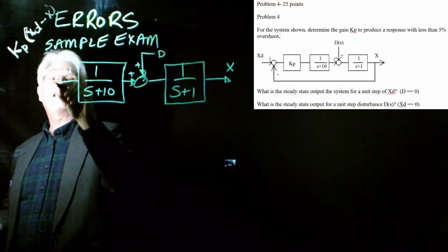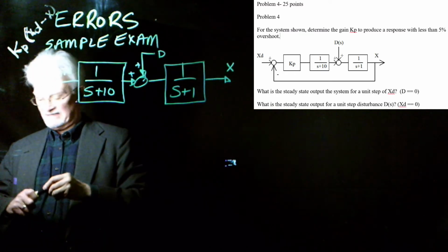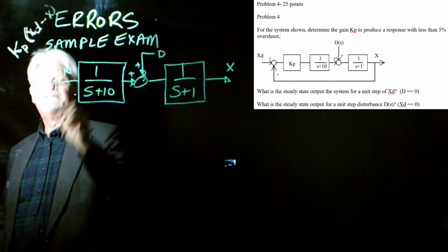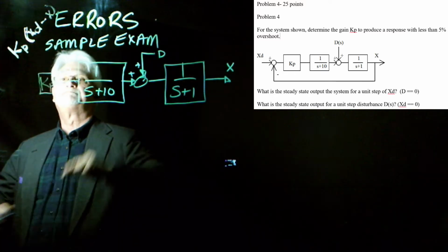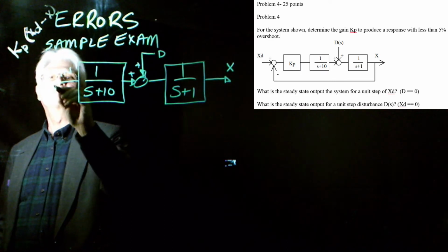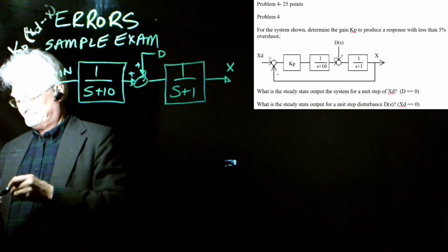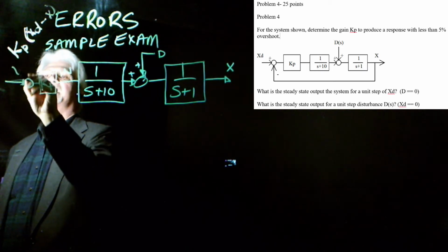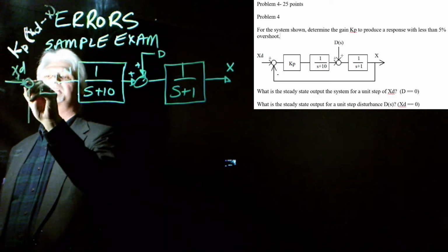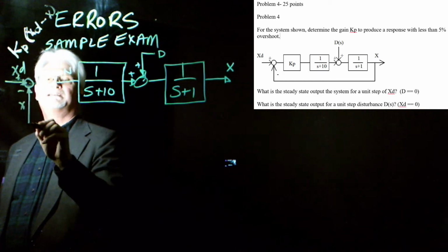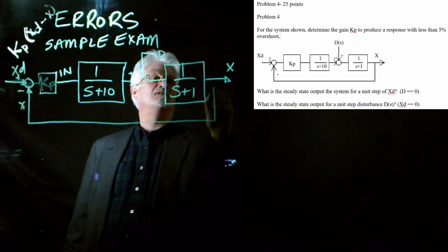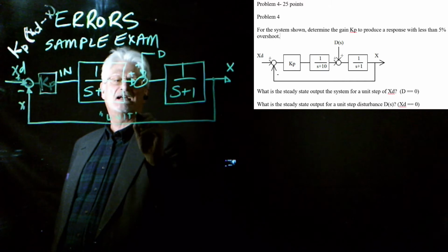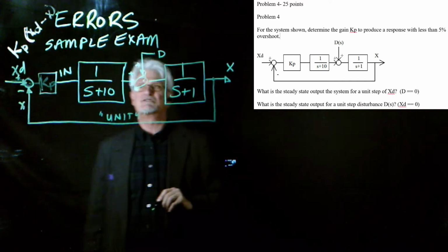So let's go ahead and do that in block diagram form. We're going to go and do that. I'm afraid that one's going to be bad too. Let's see. This is going to be Kp. And this is blue. It's not even any good. We may only have one color today. Where this is going to be x desired plus minus x. And we're going to put our feedback loop going around this way. And this is a special kind of feedback loop. It's called a unity feedback loop. It's a unity feedback loop because there's a 1 in there.